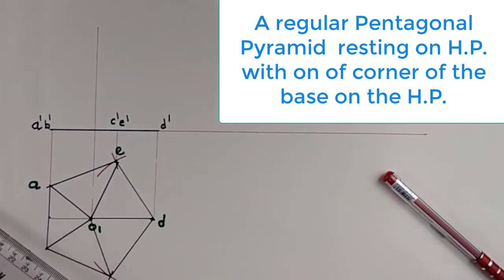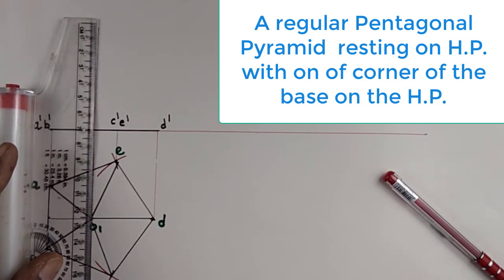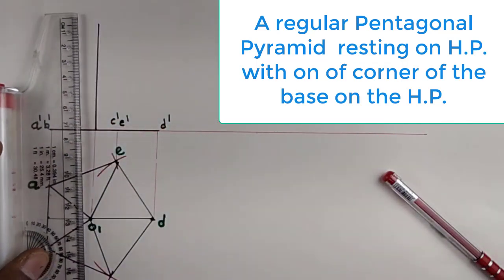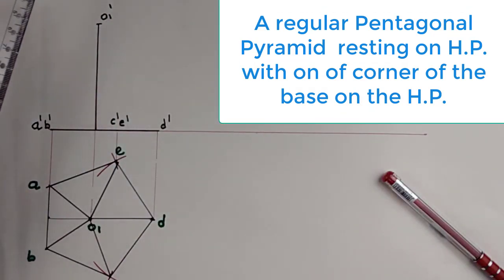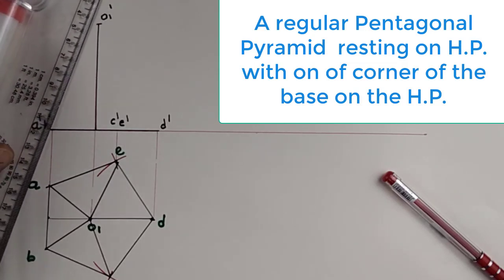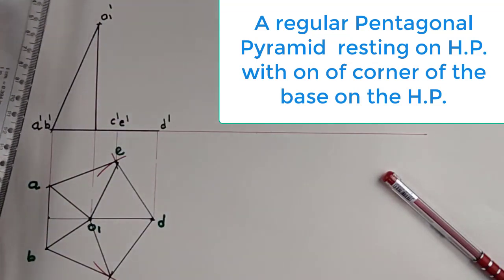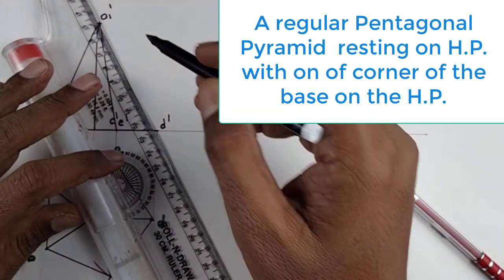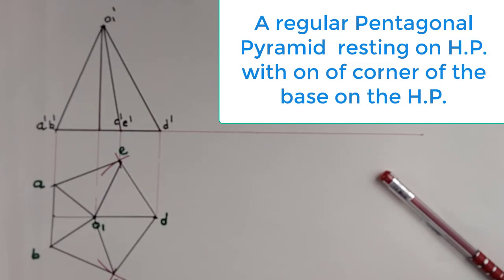I make it dark. Now the height of the pyramid is given as 70 mm. So we can mark the height on the axis. It is our apex point O1 dash. Now we join all the elevations of the slant edges: A dash O1 dash, you can join O1 dash C dash and O1 dash D dash. So it is your elevation.